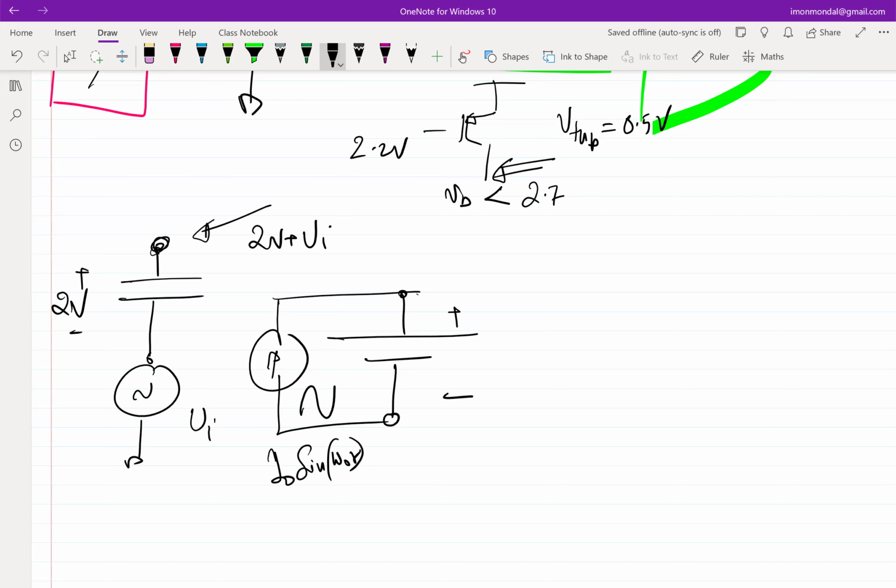Battery is holding the voltage, right? It's not allowing it to change. Regardless of whatever current you are trying to push in, it will hold the voltage, which means incremental voltage is zero. Now, what we are saying, we don't have a battery, we want to use a capacitor. So if we want a capacitor, what property of the capacitor do you know that can make the capacitor seem like a battery? Large time constant. In this case, there is no time constant associated, but essentially we see that if the capacitance tends to infinity, what is the impedance of a capacitor at a non-zero frequency?